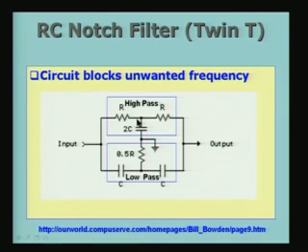When you have an AC signal passing through, the impedance is the one which is going to modify the output input relation for a filter like this. So, in the case of a high pass filter, the high frequency will pass through and low frequency will be bypassed and go to the ground. That means that what is going to come out is only the high frequency signal.